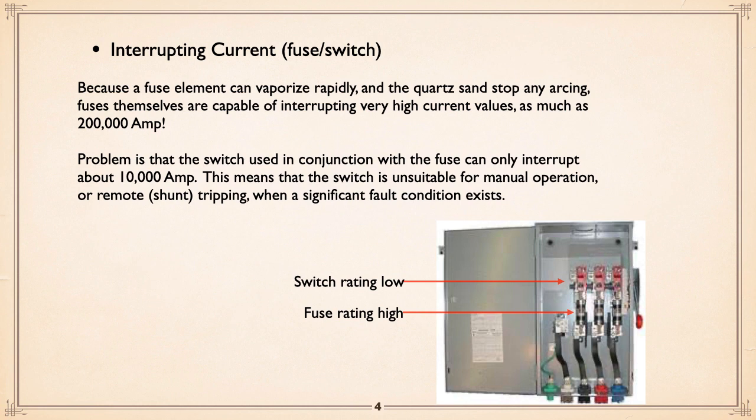There actually have been stories of a short occurring, the fuses disappearing, somebody runs over and hits the switch to turn it off, but the disconnect switch itself causes arcing, and by doing so, the enclosure becomes electrified, and the poor person trying to flip it gets electrocuted.